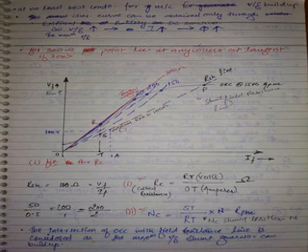So don't consider that if the resistance of the field winding is above critical resistance, the voltage becomes zero. The voltage is not becoming zero, but the voltage becomes a lowest minimum value, some minimum value. That value is the residual voltage. Remember that. When solving objective questions, if you see zero in the options, don't choose that zero for this critical resistance or critical speed, because the machine won't build up voltage. That means the voltage across the armature is not zero, but some small value.